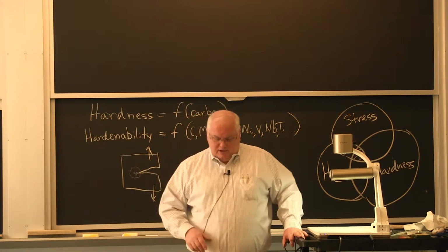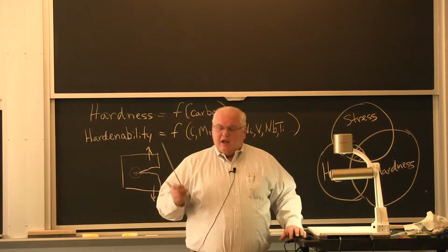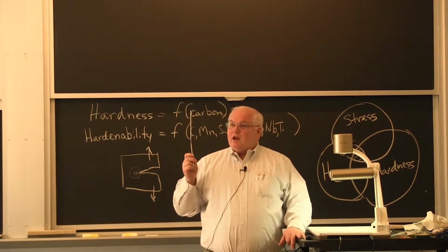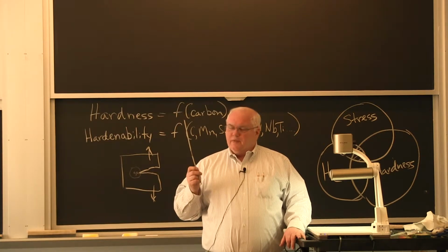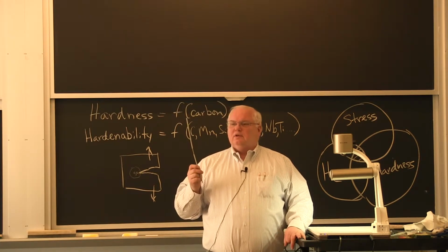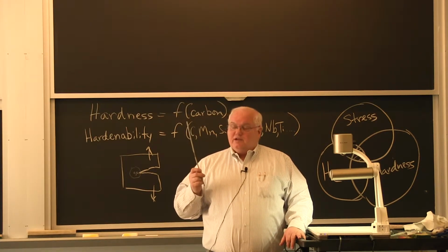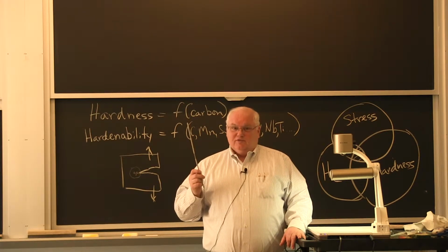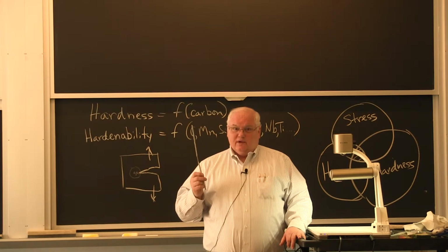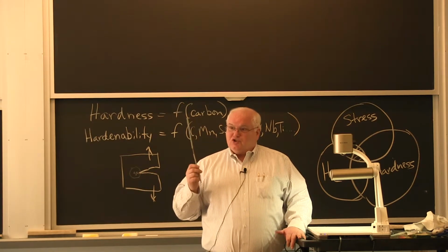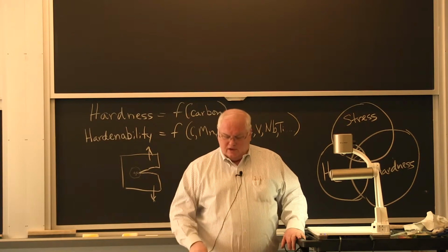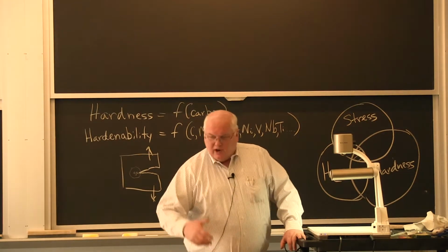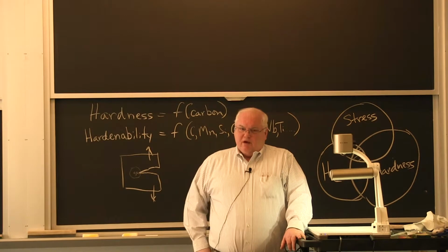And typically, the 7018s have to be kept in a rod oven at about 200 degrees or 250 degrees Fahrenheit and used, if you're dealing with a high-strength steel, sometimes used within 1 hour of taking them out of the oven, because they'll start to pick up moisture right away. And it's a question of how much moisture. I'll get into how much moisture, but I think your question is how long can I leave them out?